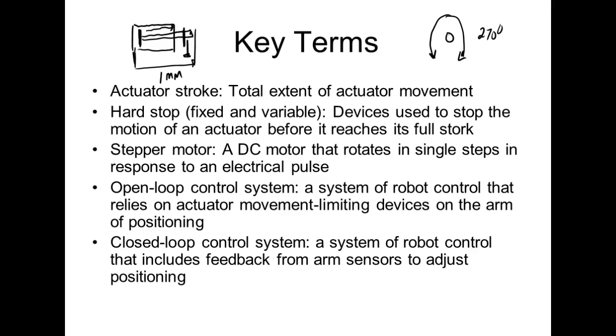What's open loop? That's where the actuators don't provide feedback. That makes sense? So one of these grippers is open loop. A while ago, when I first turned that thing on, the program told the gripper to open. But the gripper didn't open because there was no feedback, and the controller just kept running the program because there was no feedback saying, okay, the gripper is open.